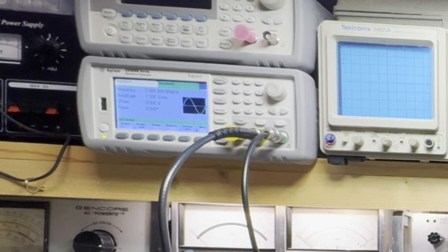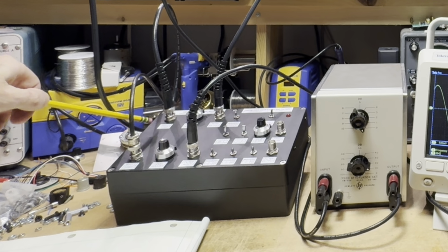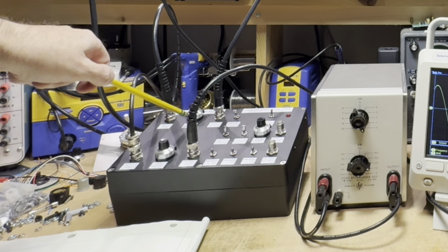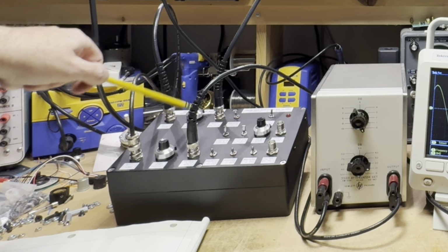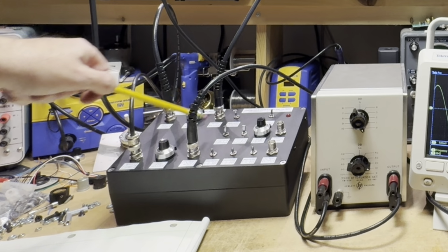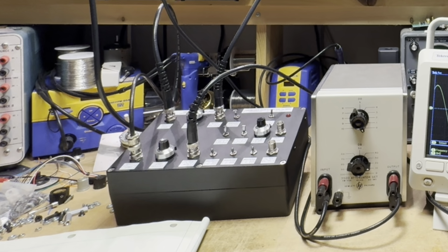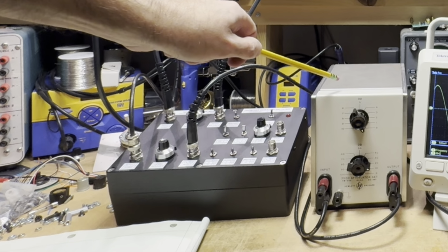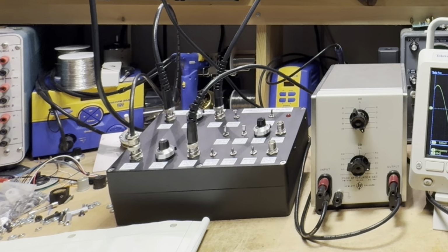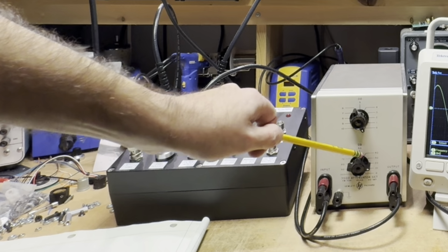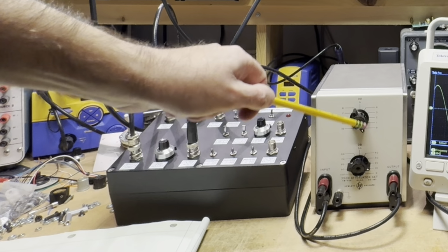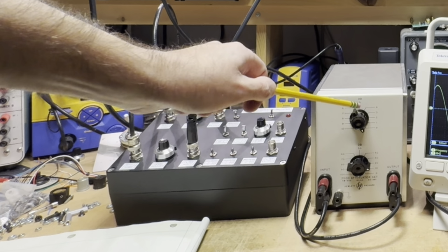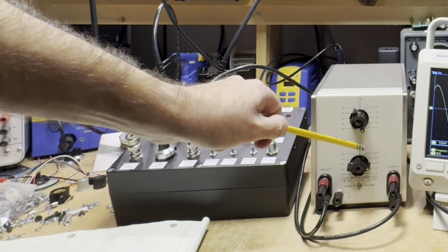Both sine waves. I've got channel 1 going into a mixer box here on channel 1, where I can vary the input level with the potentiometer, which is currently set for maximum level. Channel 2 is going to go through this attenuator box, and that's going to let me vary the level of our channel 2 signal in steps. I can go in 10 dB steps for the demonstration of measuring harmonics with a spectrum analyzer.